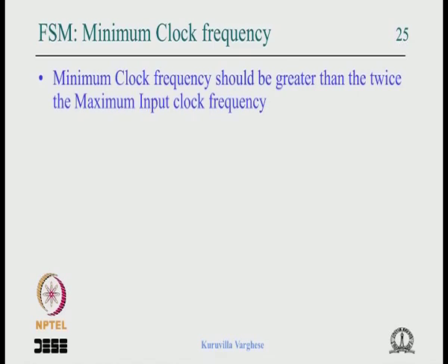It sounds like the Nyquist criteria, where we are talking about the transform, the frequency domain. You have a signal and you want to sample it, and you know the highest frequency contained in the sine wave, then you should sample at twice that so that you can recover it.